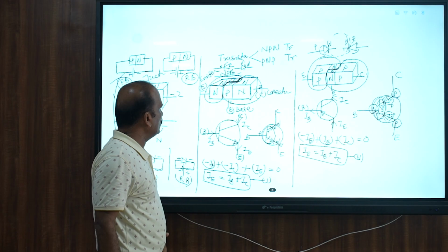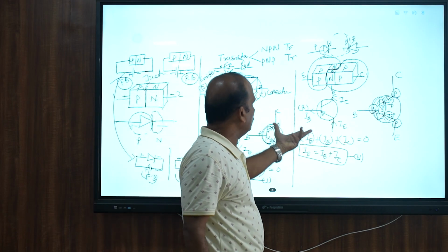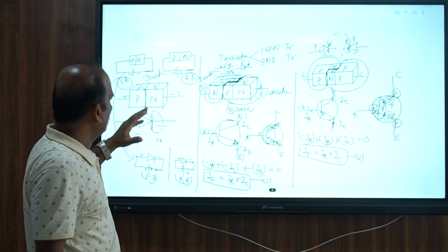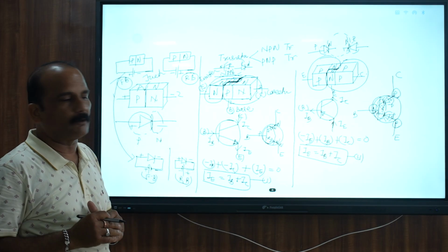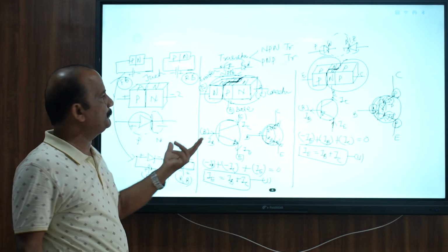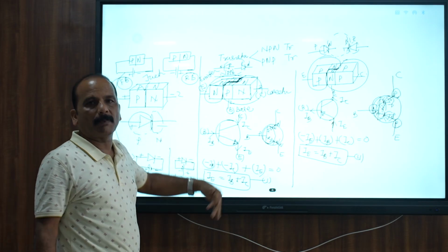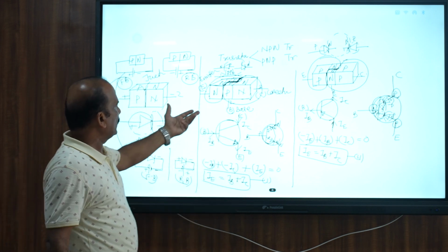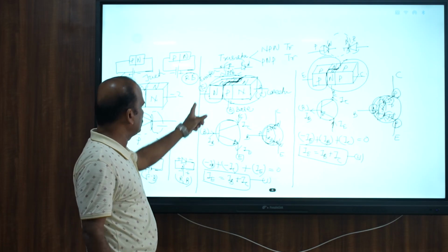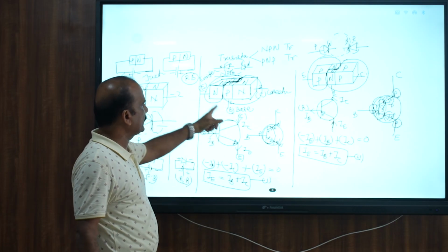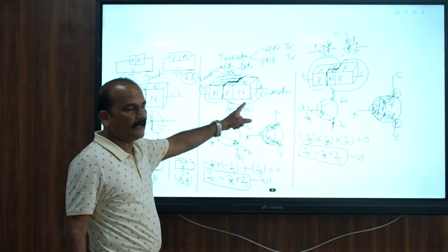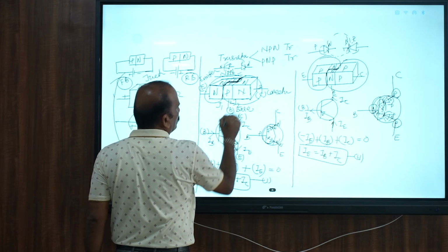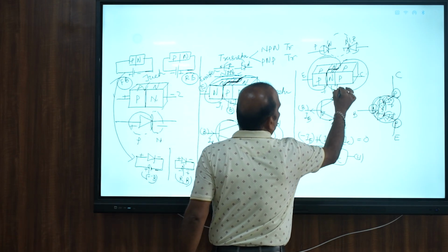So my point of view is that though it is a transistor, actually a transistor consists of two diodes, and depending upon the fashion of connection of these two diodes, there is formation of two transistors, NPN and PNP. So basically, if we convert our definition into another part, we have a definition like this. It is a three terminal device. You see emitter, collector, base. The transistor has three terminals, three layers, and two junctions. This is your junction 1 and this is your junction 2. Similarly here junction 1, junction 2.